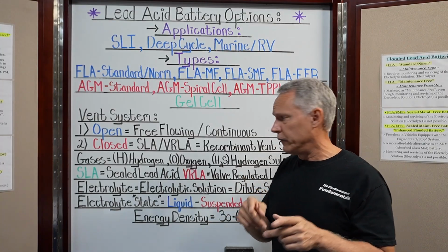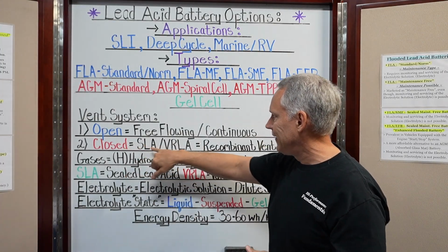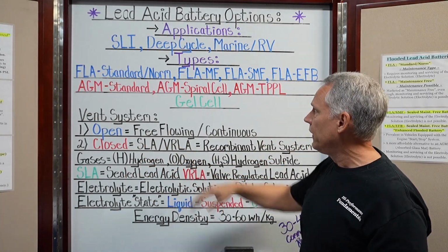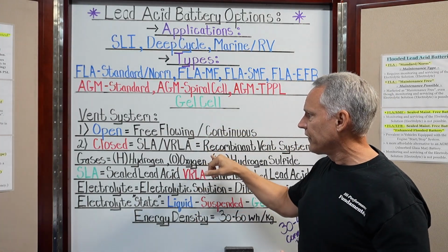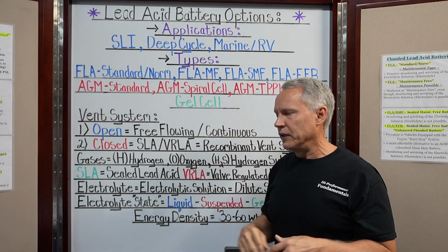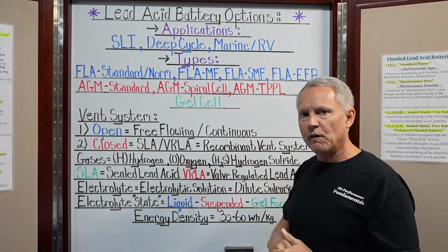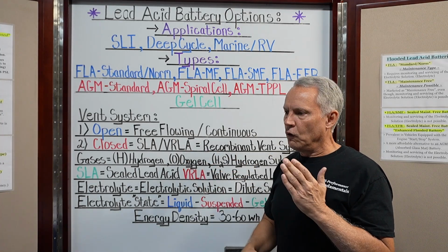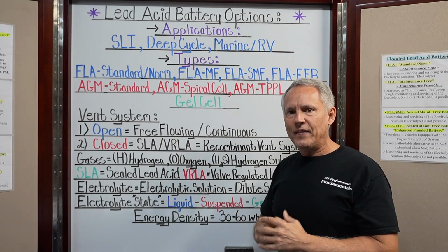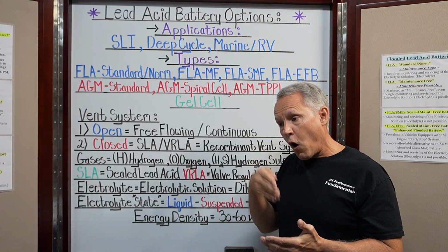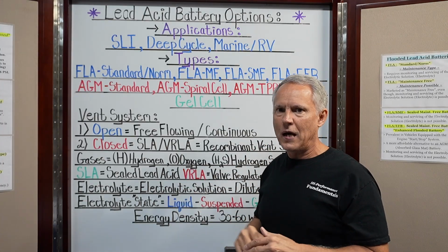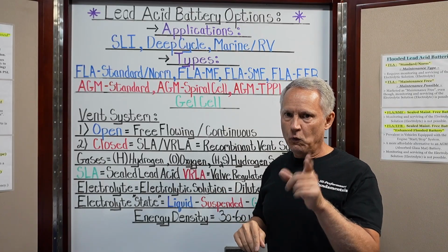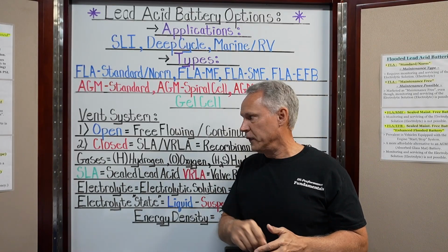And if you're a technician out there and you have a closed sealed lead acid VRLA type battery, an AGM or a gel cell battery, and you're charging it and you start smelling that, the pressure inside the battery has gotten great enough to open that valve and allow it to start to vent. So understand this, you are ruining that battery, okay? You either are ruining it or you have ruined it, right? No big deal, we'll just let it cool down, it'll be fine. No, I'm going to tell you why you're ruining it or why you have ruined it.